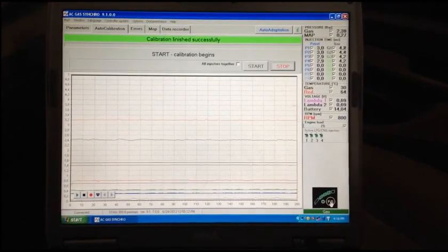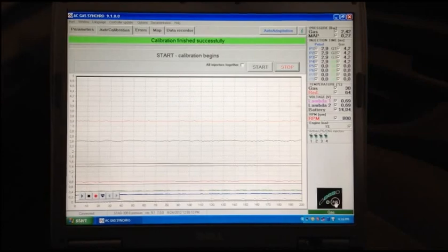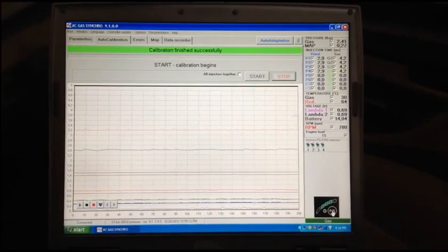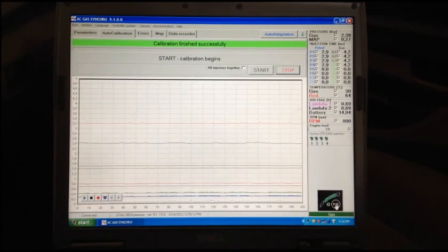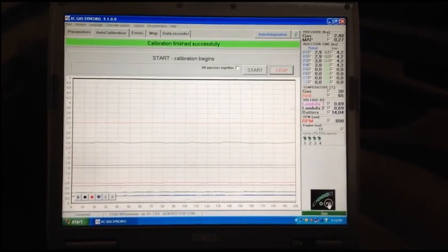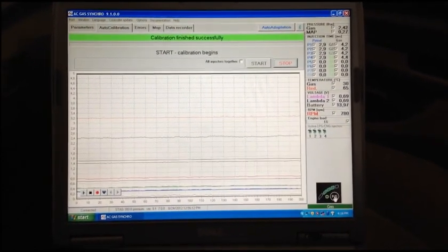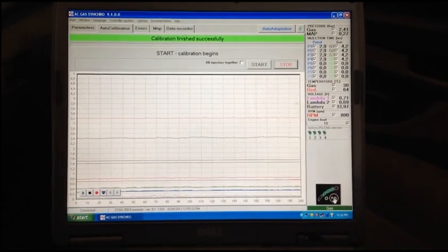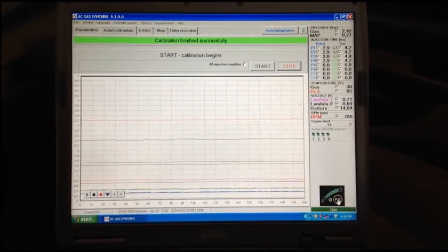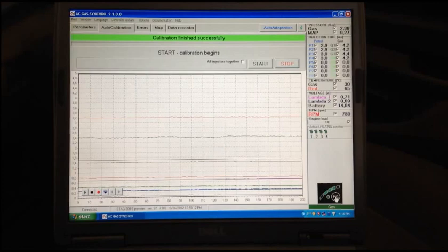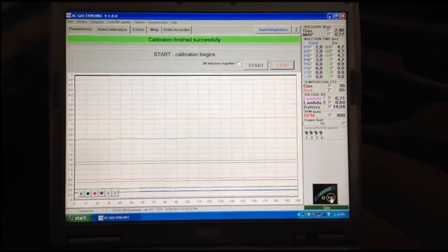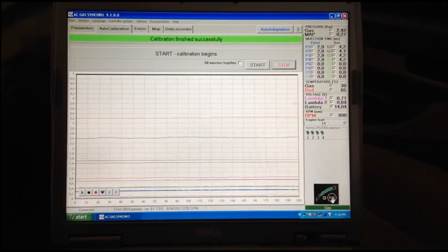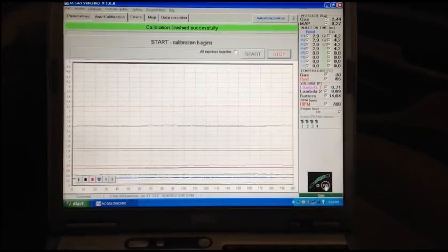They kind of bobble and pop open at uneven rates, which will cause a rough idle or a surge in your idle, and that can be corrected just like I was telling you. Some engines, this is more of a critical adjustment. Some are fairly forgiving. You get up into the larger displacement stuff, generally you're going to have the pressure turned up to 2.4, and you're going to have the injector nozzles drilled out and you're still safely up in the 4s and 5s.